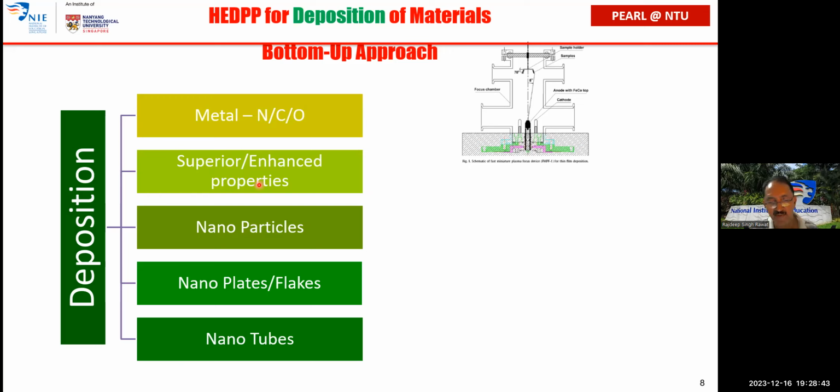So as you can guess, when you are doing a deposition, first of all the energetic ions of the filling gas species go and hit the target. So in a way they process the target surface, remove the oxide layers if there are any, or even do a kind of plasma cleaning over there. And then the ablated plasma of the metal that you have placed at the top of the anode reaches over there, and that gets deposited. And the next shot when you fire, again the energetic ions go up there, process it and deposit it. So in a multiple shot deposition, you are doing deposition plus processing, both of them together.